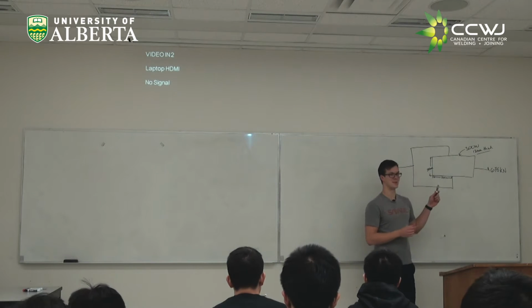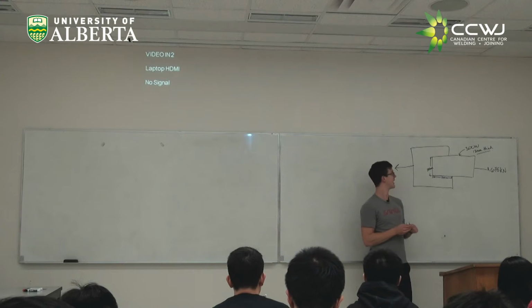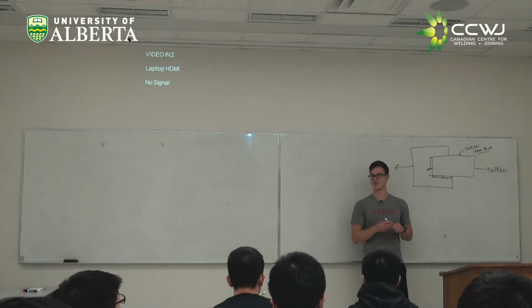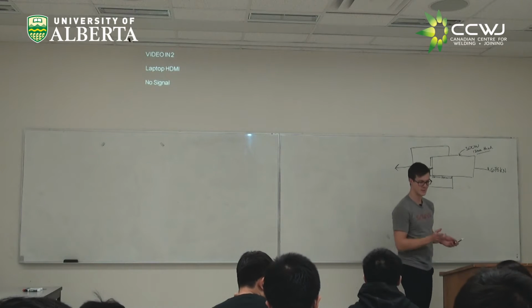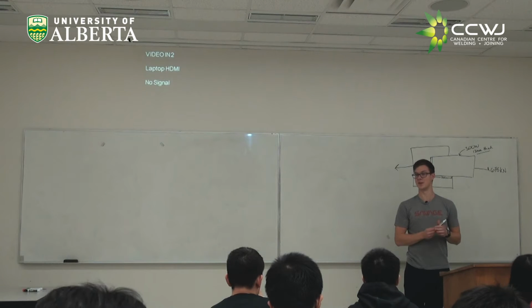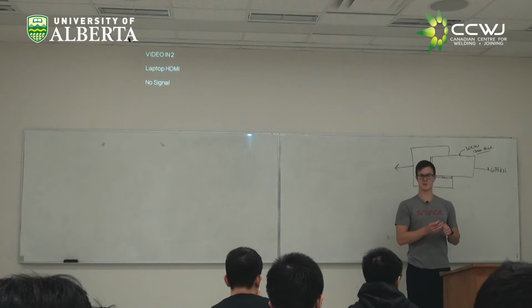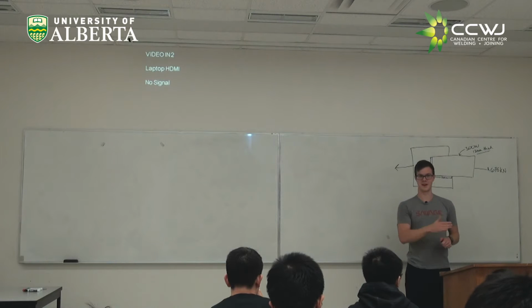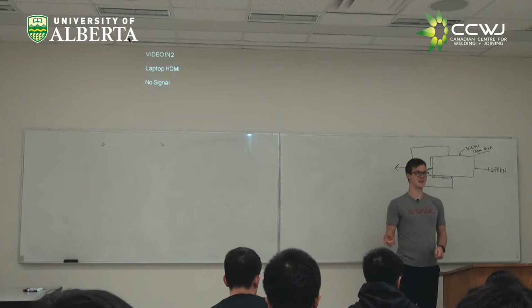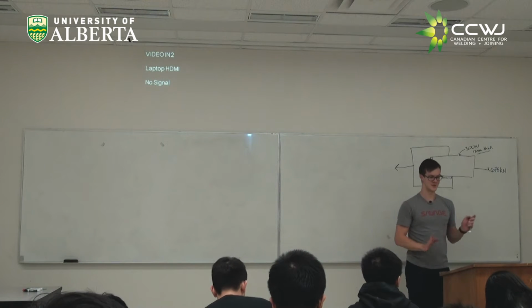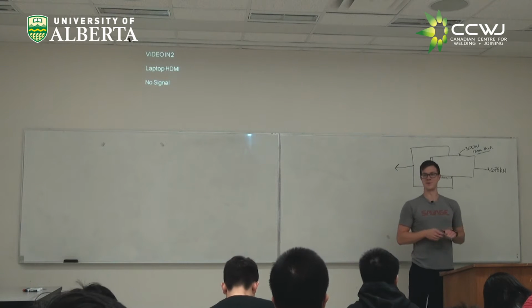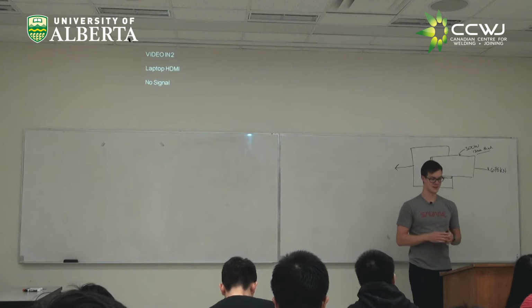This is more than 6 millimeters. T minus 2, I heard that somewhere. The maximum is going to be 10 millimeters, right, for a 12 millimeter plate. Hopefully if you go through the notes you'll remember those rules. I believe the CISC guidelines are always going to be provided in the formula sheet. So it's just knowing you have to pull that 12 millimeters, go to those guidelines, and pick the right number off the chart. Hopefully that's going to be the easiest part of this exam, if you get asked what are the minimum and maximum allowable per the guidelines.